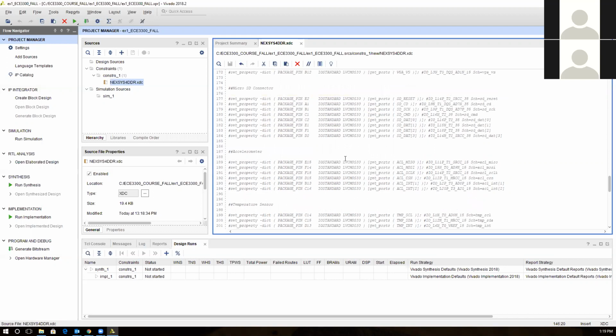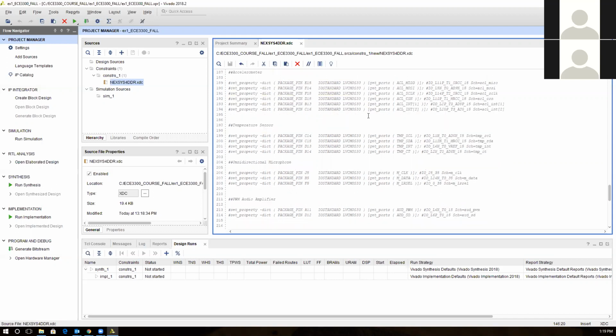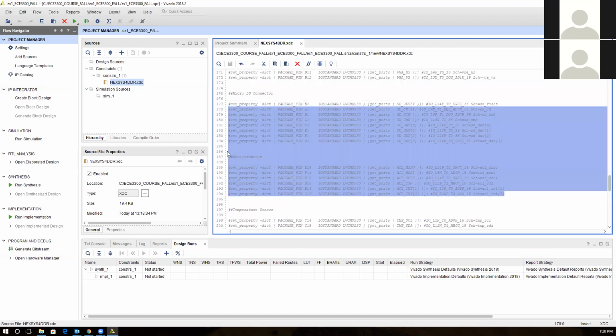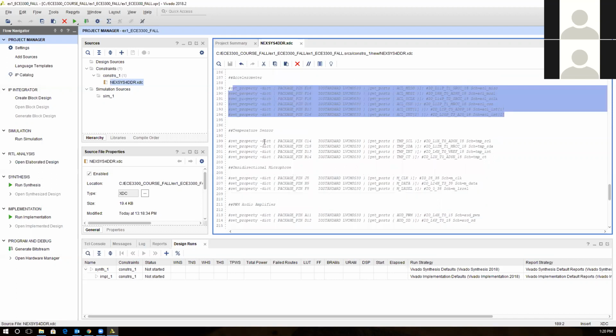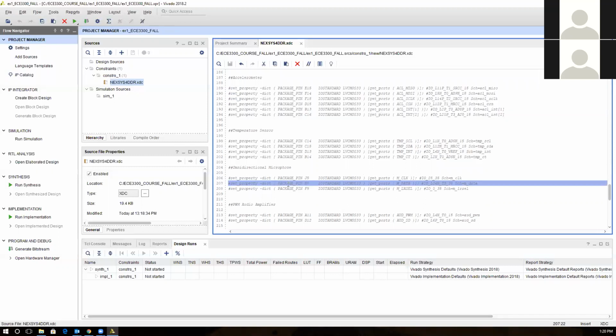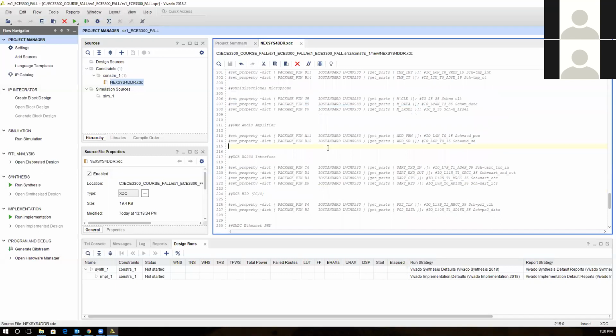And there is an SD card here in the back of the FPGA you can find. There are accelerometers, as I mentioned to you on the board, and those are using SPI. And then there is a temperature sensor using I2C, as your colleague mentioned in the beginning. And there is also a microphone you can connect and work with. And there is audio PWM, pulse width modulation.